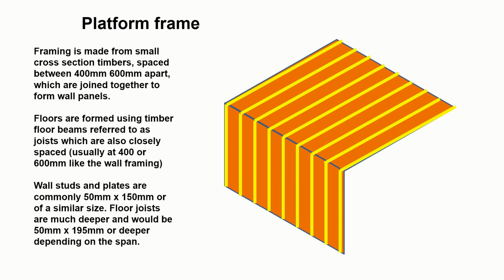If you refer back to the structural lecture where I was talking about bending, the possibility of a joist bending relates to its cross section. The deeper it is, the less that bending will cause the ceiling to sag. And if a joist does sag, then ceilings will crack and decoration will suffer. So they tend to be slightly deeper depending on the span.